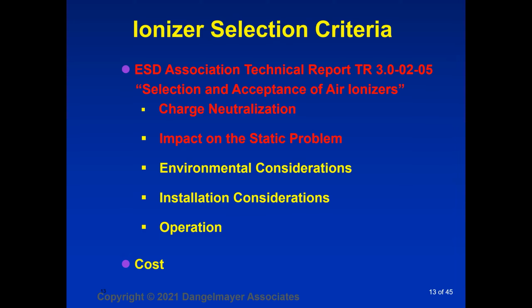It says ionizers should do something. Also a very interesting approach to the matter. We basically say that if you're going to use an ionizer, you should be able to demonstrate that something in your ESD control regime has changed because of the ionization being present. We'll talk about that in a little more detail in a moment.